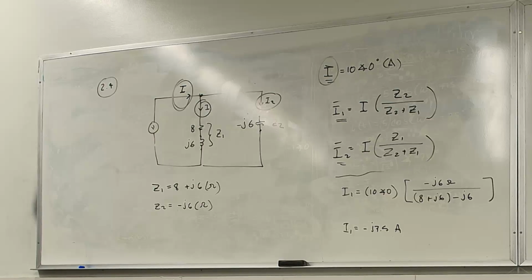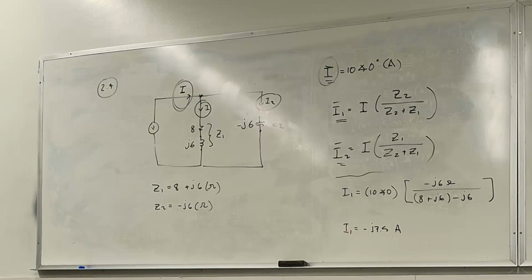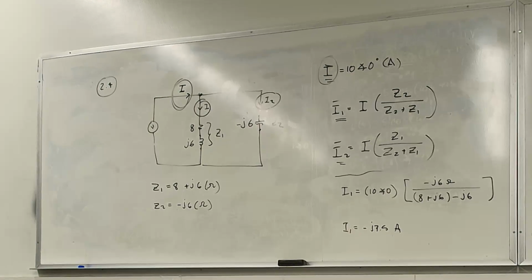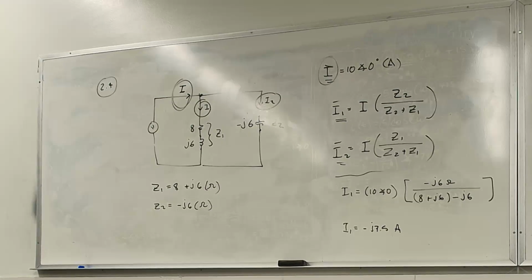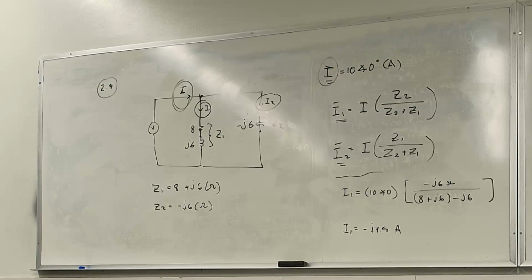I know this is the current on the capacitor, and I know that's a purely capacitive circuit. So if I go by the rules that have been given to me, a capacitor current should lead by what? 90 degrees. So you'd expect the voltage, once we get it, to land somewhere here, perpendicular to that. You agree with me, everybody?